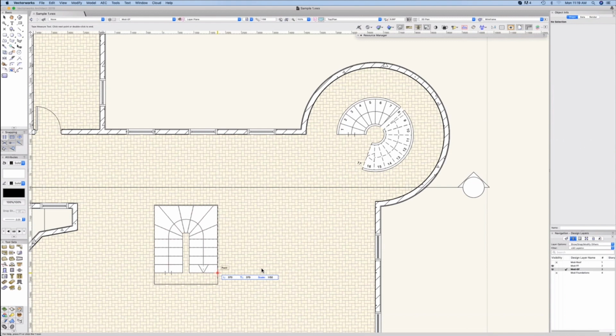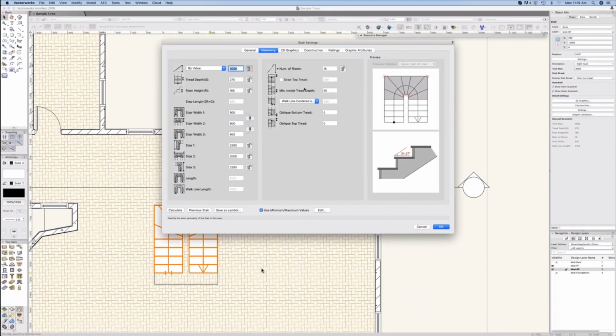The nice thing with D is you can measure several clicks and it will measure the total length. So sometimes you want to measure almost like a perimeter of a room or something. It gives you the length and the TL, the total length. It's quite useful for measuring how much finishes you need. So double click, 370 in there.